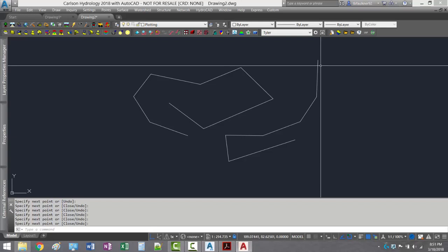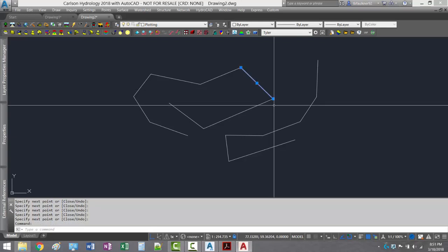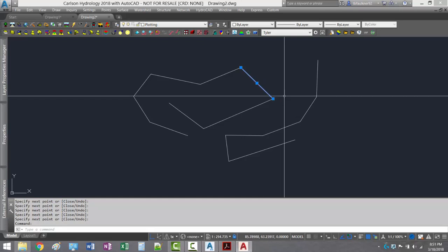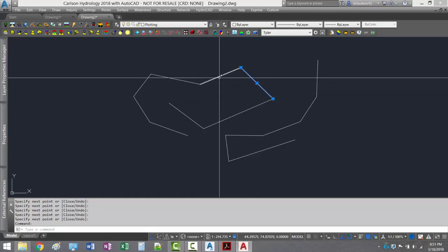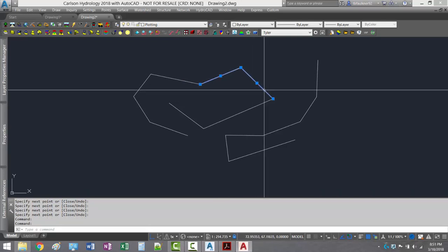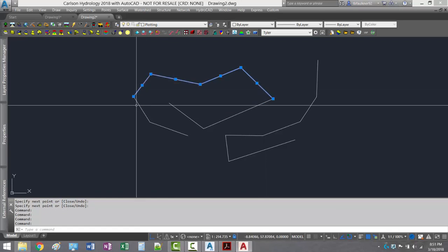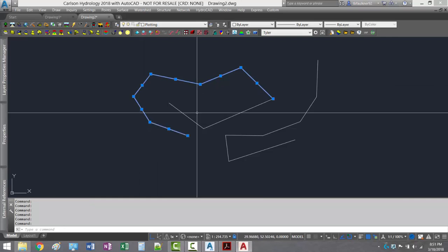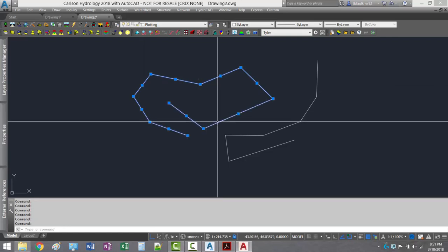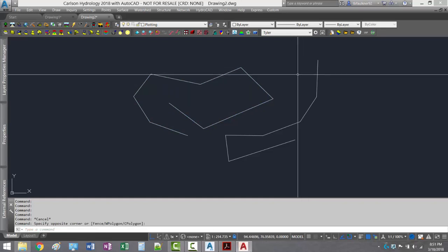And actually, selecting can be a little tricky in CAD. One way to do it, if I just pick on a line, notice right there, it just highlights that one segment in blue. Now you may be used to picking on something else, like if I pick over here, deselecting what I had before. In AutoCAD, anytime I pick, it's constantly adding to the selection. So I don't have to hold down the control key to select multiple. The program knows I'm continually building up what's called my selection set. If I hit the escape key, it clears out my selection. I'm just back to it.